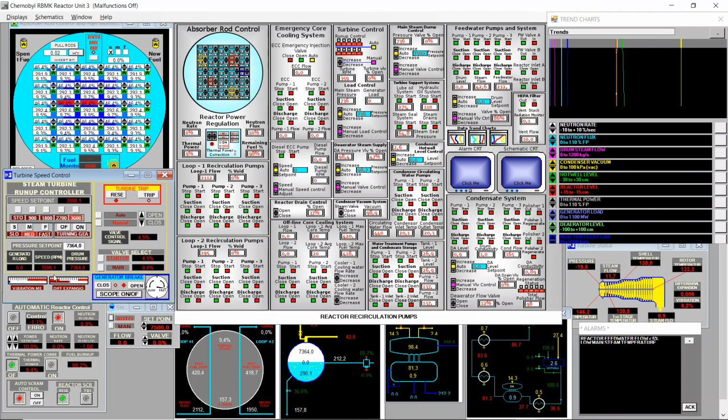We're at 4.5% now, and I will close. No, I cannot close now yet. I need to increase. Okay, now I will close at the top dead center. Perfect. Now we are on grid. The generated load is 0.1 megawatts, and we need to increase power set point now to 15%.